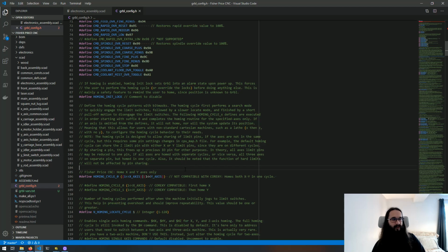And also, if the laser output is connected to the z-axis input pins, and the z-axis stuff uses an internal pull-up, that just kind of means the laser would be on all the time, which is kind of stupid.